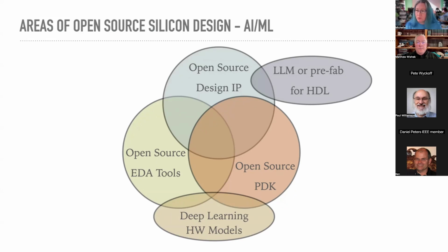And we have a little bit of experience with two subcategories. One is MATLAB's HDL Coder, which lets you take a Simulink model and convert it into HDL. We have tried this a couple of times, and we now have some recommendations. We can recommend that HDL Coder does work to produce HDL, human readable HDL that is fairly high quality. It does what it's supposed to do. And the process is lengthy. We're talking like 12 to 20 steps in MATLAB to get this toolbox to produce the code.